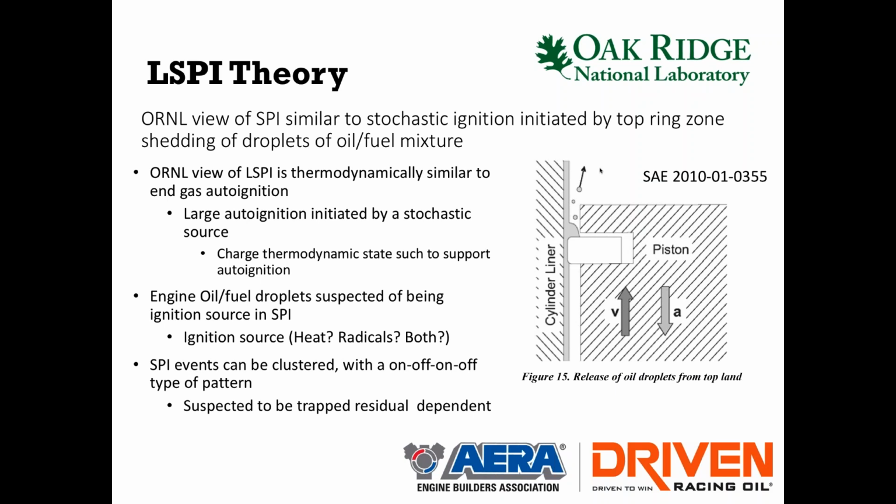We were able to prove that out on a different engine just by changing the exhaust manifold and improving low speed scavenging. We were able to change the knock tendency of the engine, all other factors held constant. So there's definitely something to this. We don't have all the answers by this point, but we are certainly starting to be able to validate some of these initial theories that came about several years ago, and the testing says, yep, this is what's going on. It is the oil and the fuel mixing, and it is dependent upon the trapped gas.